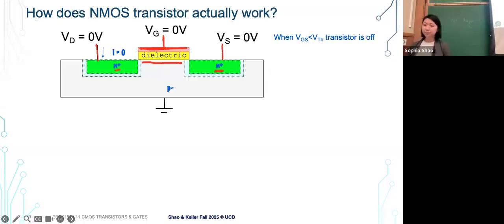the transistor layer. So I mentioned earlier, when the gate voltage is low, in particular less than the threshold voltage, we'll talk a little more about what the threshold voltage is, but when the gate voltage is low, let's say 0, nothing is going on. It's a capacitor, things are not conducting, and no channel exists between the drain and the source, so there's no current flowing through our transistors here. Let's see what happens when we apply voltage to the gate terminal.